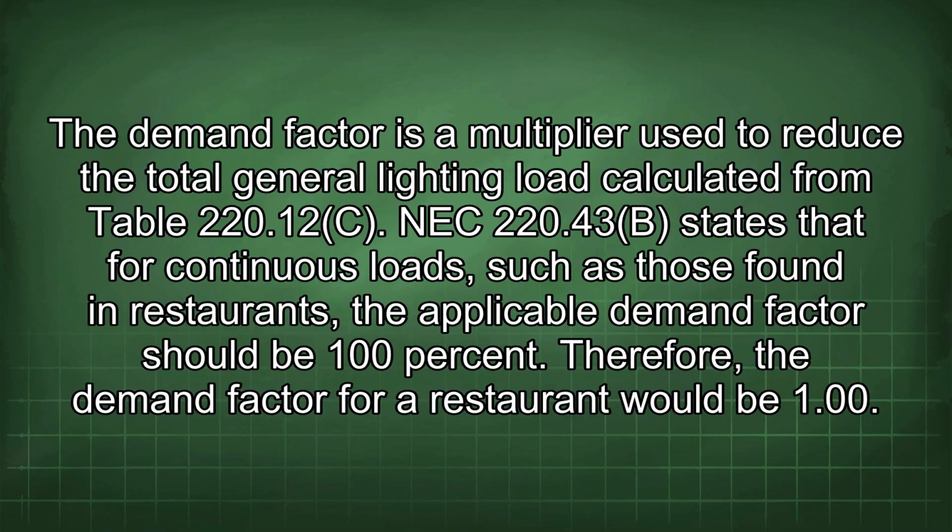NEC 220.43(B) states that for continuous loads, such as those found in restaurants, the applicable demand factor should be 100%. Therefore, the demand factor for a restaurant would be 1.0.